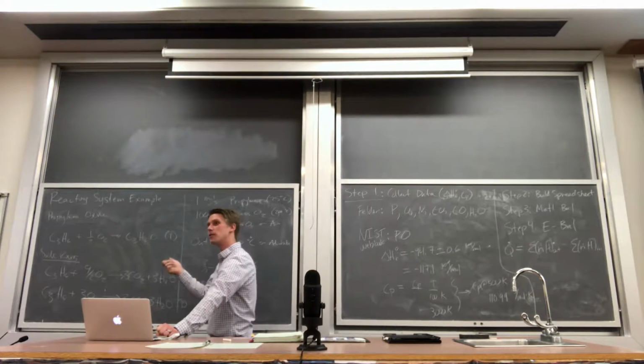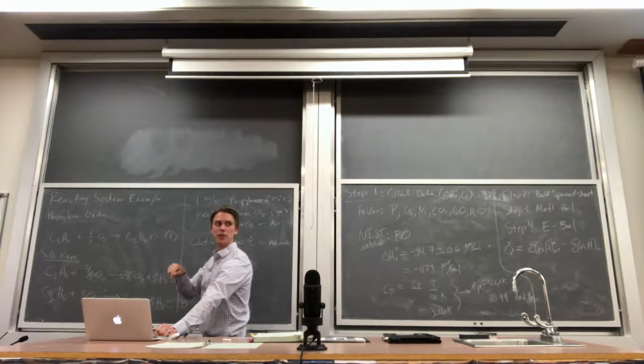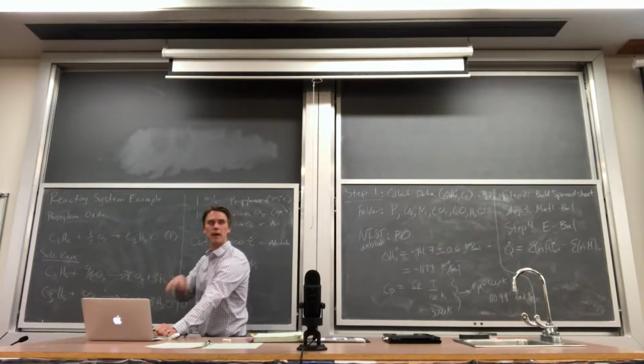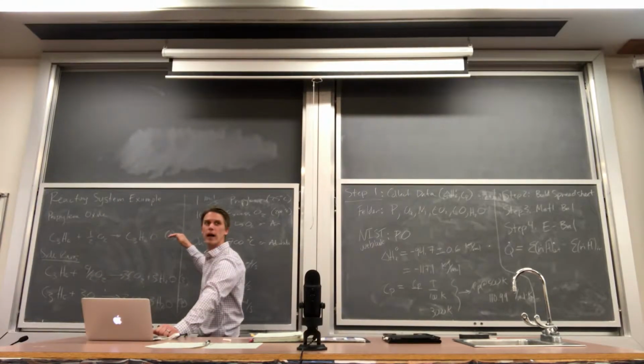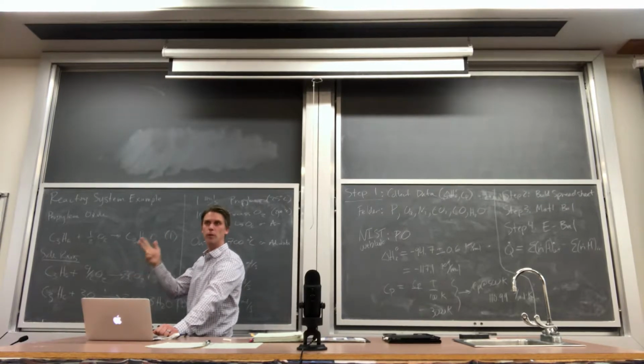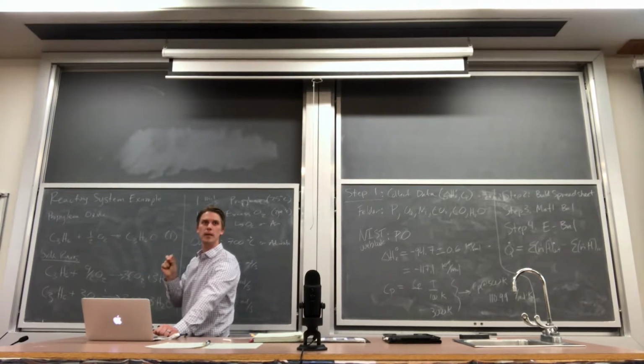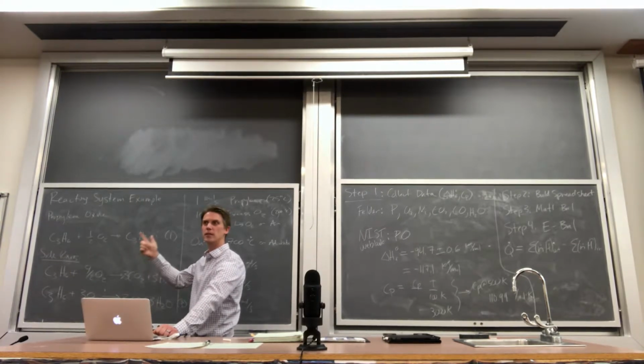As the equilibrium constant changes, the extent of reaction changes. As the extent of reaction changes, the heat requirements change. So all of these are tied together. Eventually, on the last homework problem, you're going to have a question where you have to do the material balance, the energy balance, and the equilibrium all together at the same time to find out what the system would actually go to. Right? Integration of mass, heat, and thermo all together.